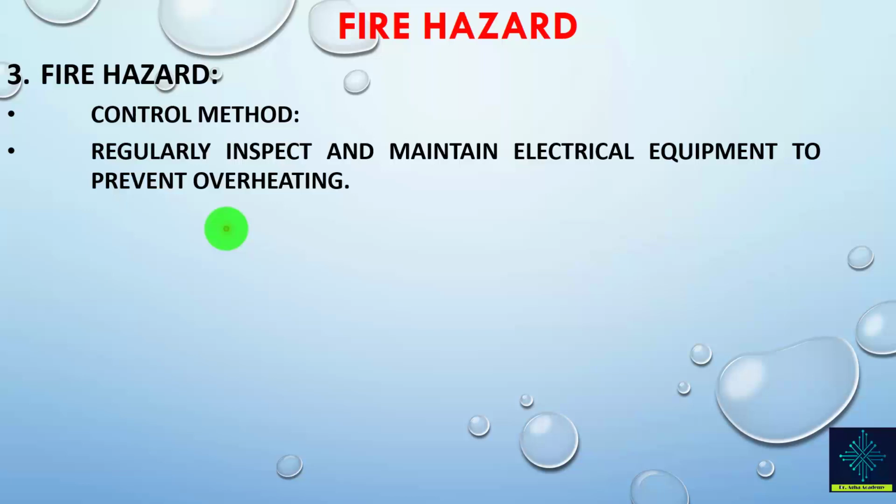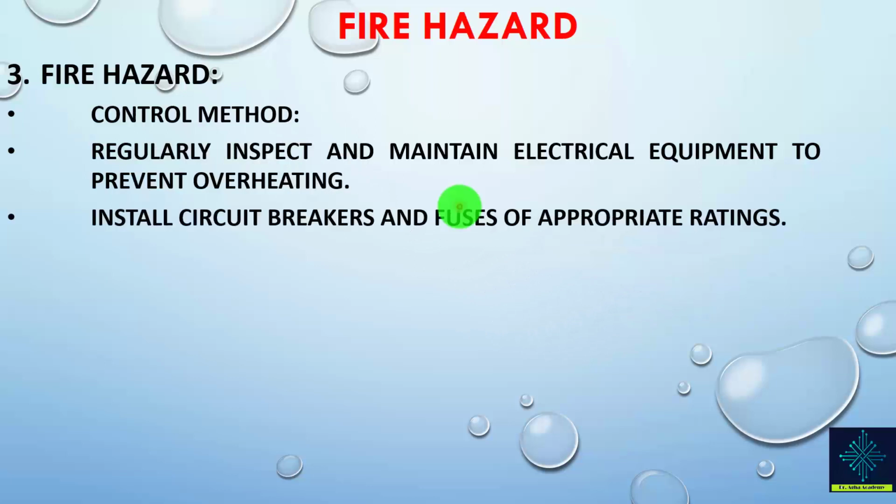The control method includes regular inspection and maintenance of electrical equipment to prevent overheating, and installing circuit breakers and fuses of appropriate ratings.